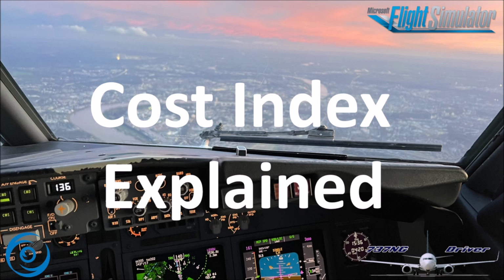Also note that the true airspeed is higher at flight levels around level 300 than at, for example, flight level 400. So in general, if you do want to go faster, anywhere around level 300 you're going to get the highest true airspeed out of a given Mach number.